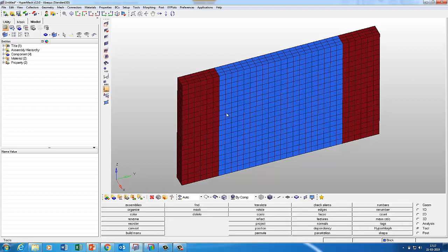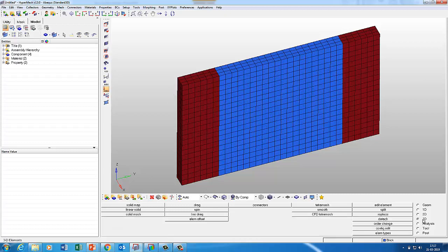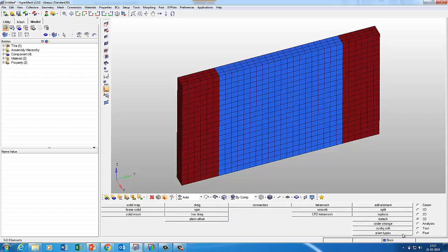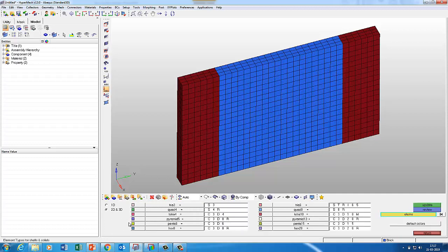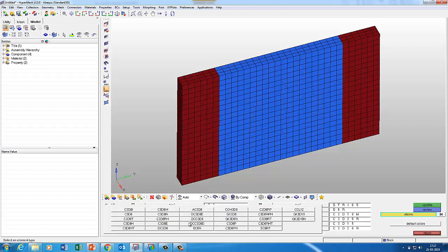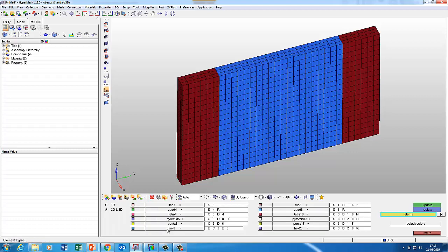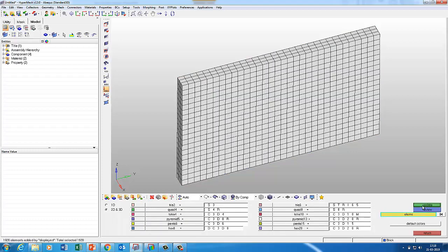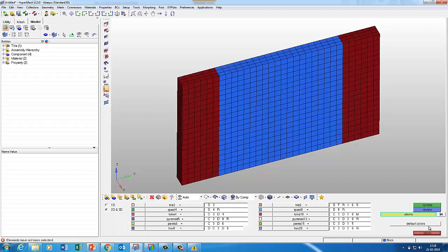So we have everything given now. We also got this cross sectional area. We'll just select the right solid element. So you go to the 3D panel, you go to the element edit, you go to 2D, and then you select DC3D8, which is a heat transfer solid element. So we update it.